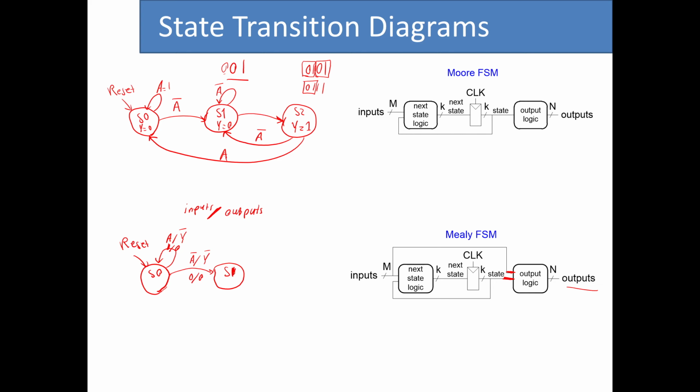So now we are at the state 1, which means that half of the pattern is being detected. So what should we do if we detect another 0? We should remain in this state. And this is similar to what we had above. So when we detect another 0, we stay here and the output is still 0.